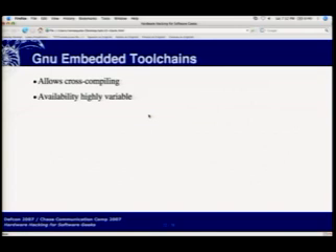What this allows you to do is, if I've got GCC that cross-compiles to ARM, I can make an ARM binary, load it onto an ARM chip, and have it run natively. That's very important because none of these microcontrollers will use the same instruction set as my x86 laptop, because x86 is almost never used in embedded applications just because it's overkill. It has an overly complicated instruction set, a lot of pins, just a lot of legacy stuff in it.